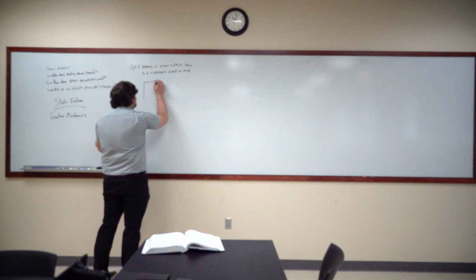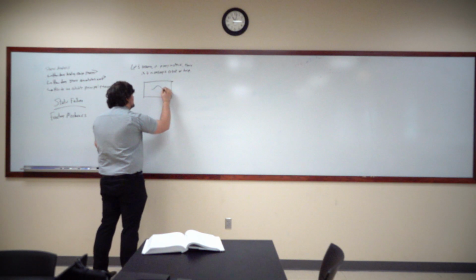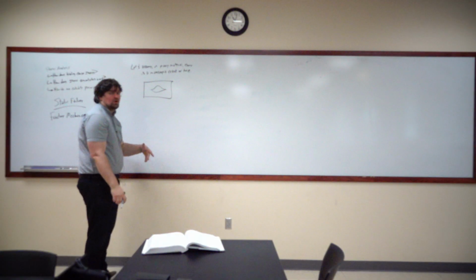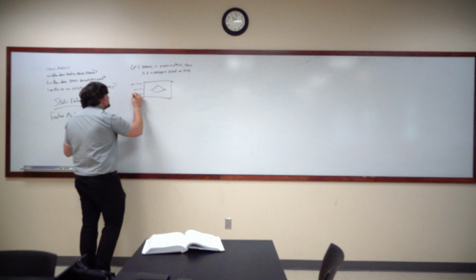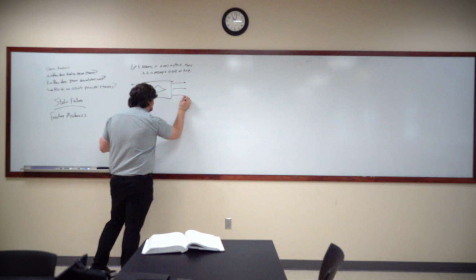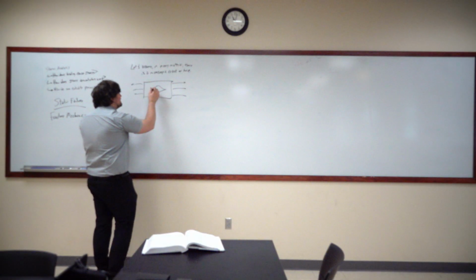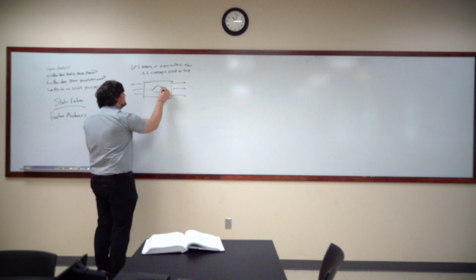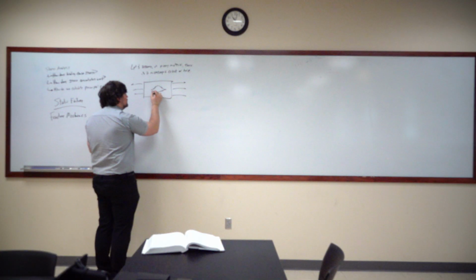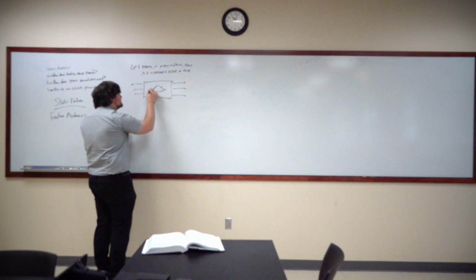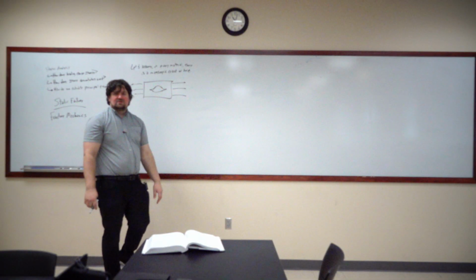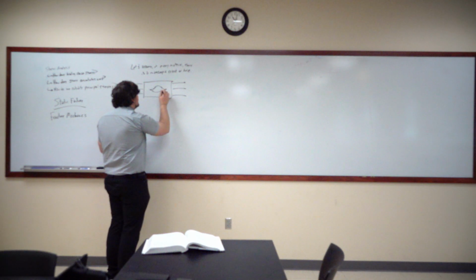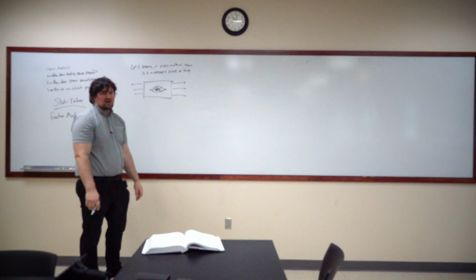And so we're going to go ahead and draw our material, and then in the middle we're going to have some kind of a microscopic crack or hole. Now, in this system, if I apply a load in this direction, a tensile load, what's going to happen is you're not carrying any of that tensile load on this piece of the hole. Okay, you're going to have some stress concentrators here and here because of how large it is, but ultimately right in the middle, this part here does not carry any load.